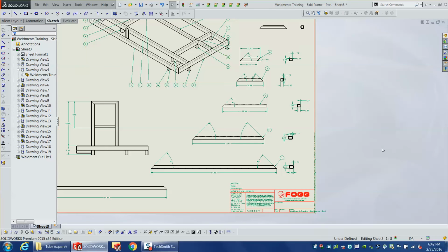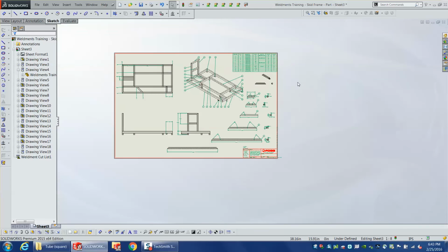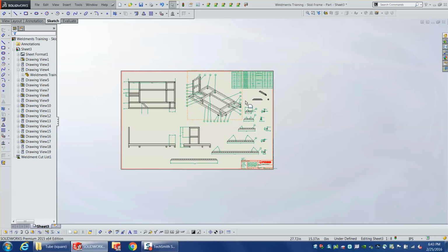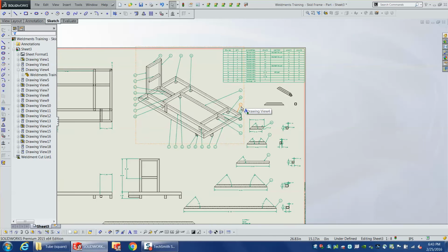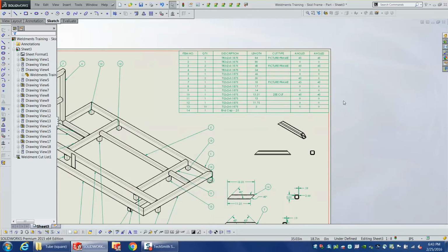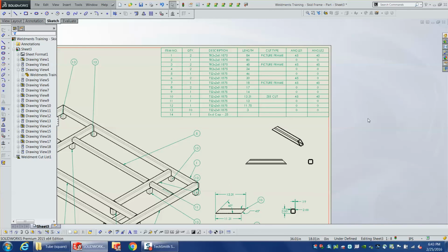I'm not sure if you could. That sounds kind of backwards to me. I don't know why you would want the part to talk to a cut list. I do height, profile, area, height, thickness, and length in one line. Oh, I see. You want to separate the length out, because it's not the full description. I would probably use a custom property in the part to combine those instead.